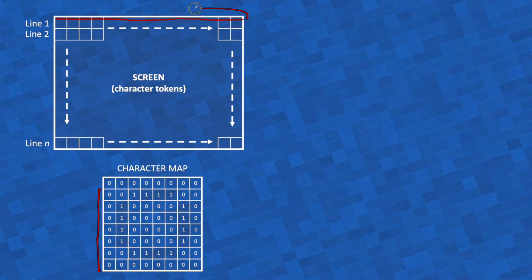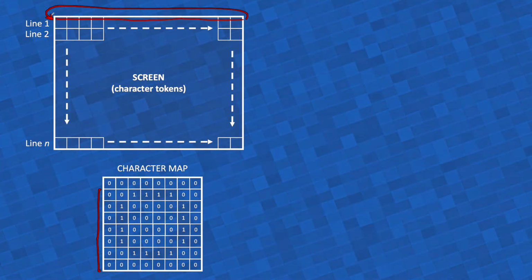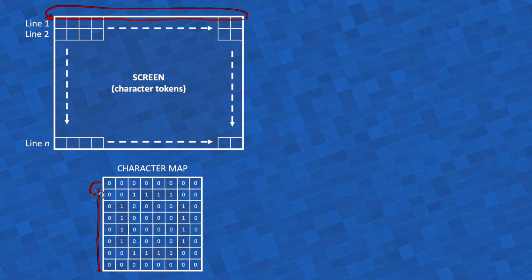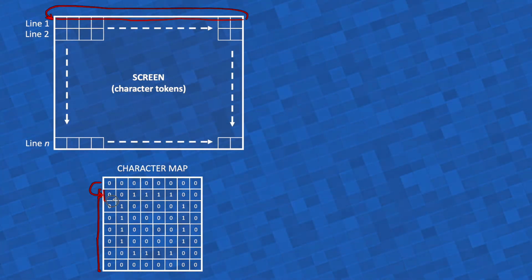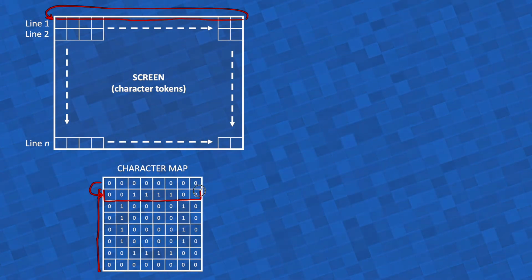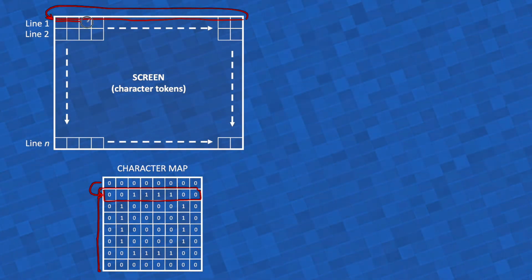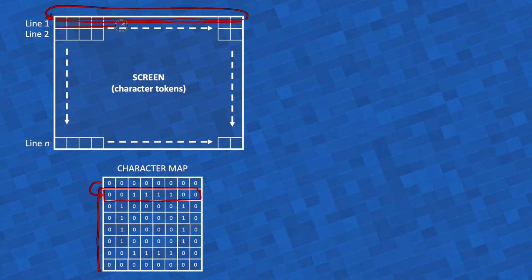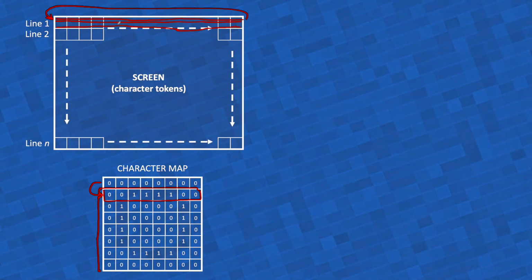So what it has to do is go back to the beginning of the line, to that first address of the line, and do it again, but now index and increment some pointer to tell it that it's now reading the second byte of each respective character. So it will then print the second line here. And it will do that 8 times until it writes the final line of each character in that token line.